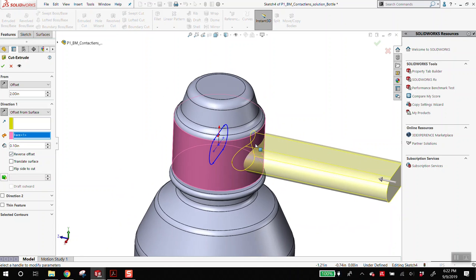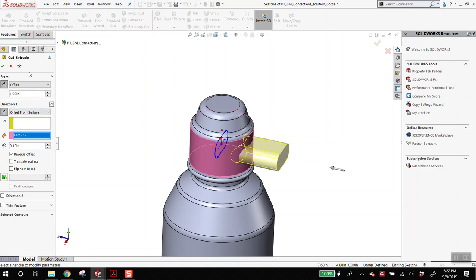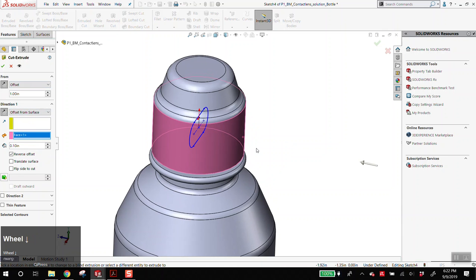It is going to be recorded, but again, it's a simple extrude cut using all of these settings. So once again, we start by saying where we want the cut to start from, which in this case is 2 inches away from the model. This is somewhat of an arbitrary number. We play with this to get the direction of where we want it. We then change the setting from blind to offset from surface. It's asking us which surface we want.